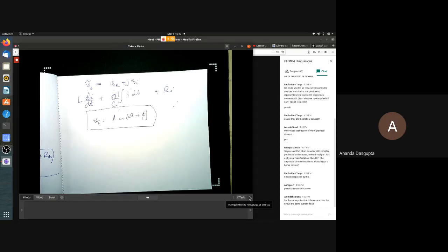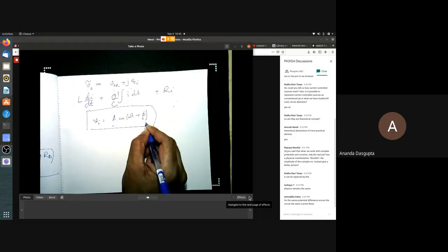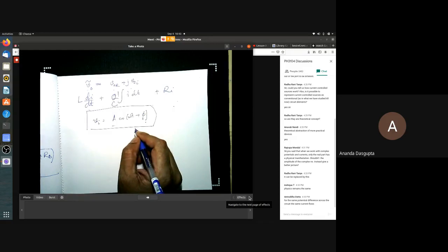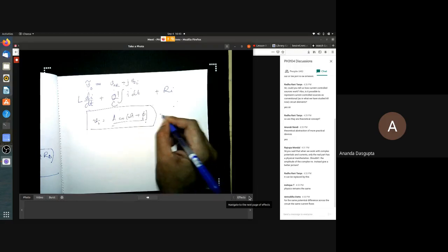And by the way, cosines and sines are all the same. All you have to do is change the phi. So because of Fourier series, if you know how cosines behave, you essentially know how the circuit behaves for all signals. Now this is what you really have. It's not as if you had a complex function whose real part or imaginary part or magnitude you can choose. This is what you have. This is where you start.